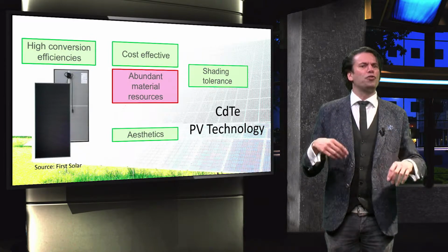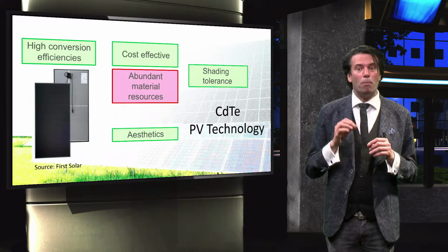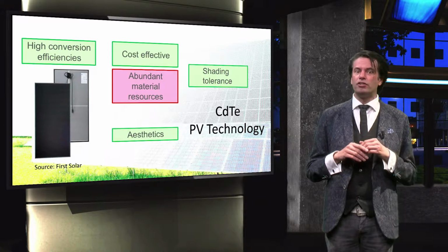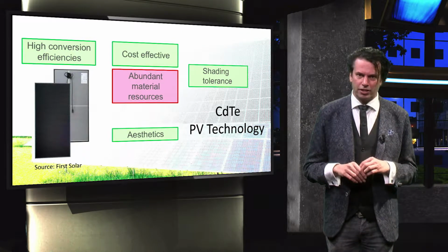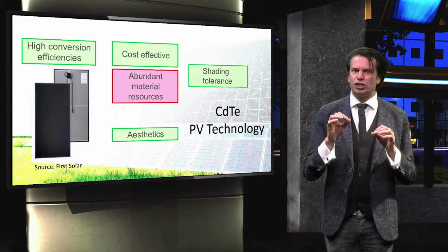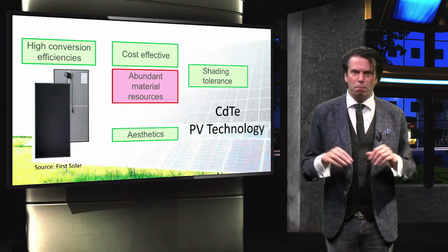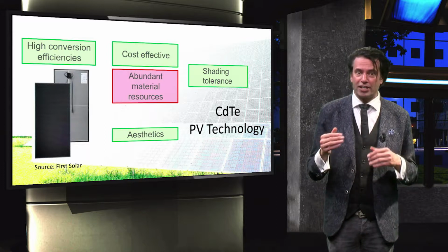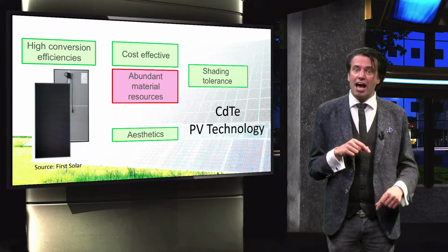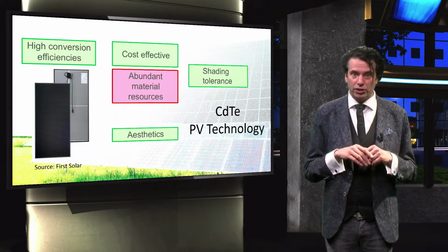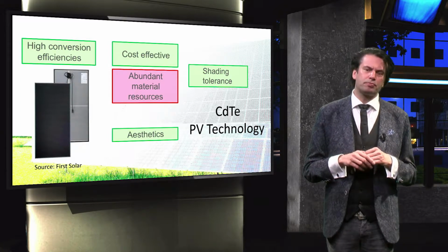Another advantage of all thin film PV technologies like cadmium telluride is that due to the typical monolithic interconnection schemes of the individual cells and modules, the modules are less sensitive to shading effects. If the edge of the shade is perpendicular to the length direction of the individual cells, the output power scales roughly linearly with the fraction of the module area that is not shaded. Wafer-based modules have a step-like relation with the illuminated fraction of the panels and result in lower performances.